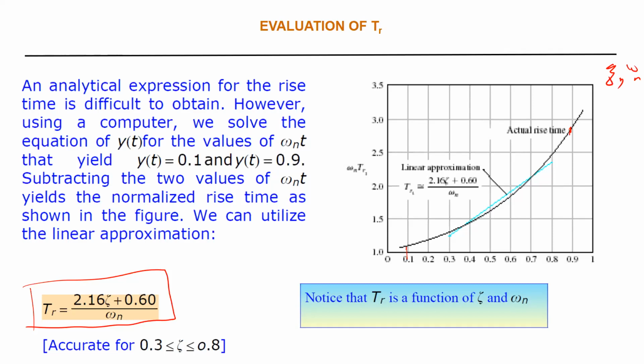But we cannot use overshoot, rise time, and settling time together to get zeta and omega n. That might conflict. Okay? Any question here? And we use two, Doctor, to get zeta and omega n, either rise time with settling time or settling time with... Yes. Hopefully that will give you the third parameter depending on your calculation.